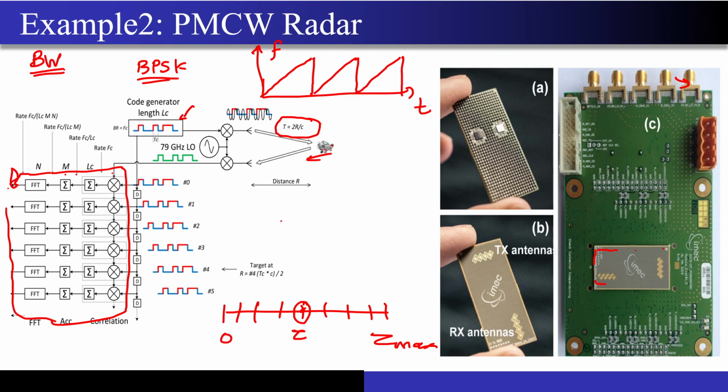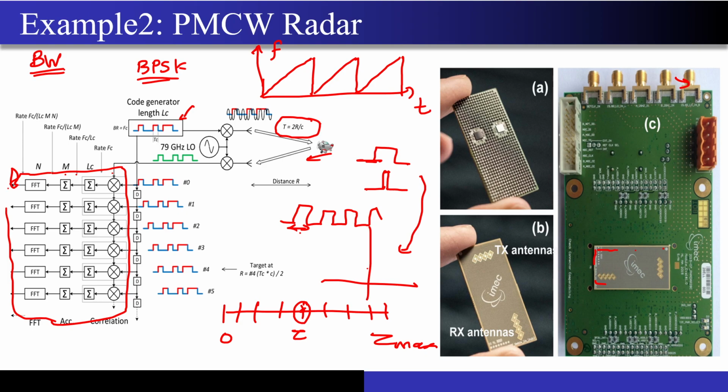So now the code that you are sending over here, if I reduce the duration of the pulse, if I take one pulse like this, and another pulse which has a very small pulse width, and now I take the Fourier transforms of both the pulses, in one case I will get a very wide sinc lobe, and in another case I will get a very small sinc lobe. I am just drawing the main lobe of the sinc function. Okay, so for this smaller width pulse, I will get this huge lobe over here. Correct? So it means that it is achieving a higher bandwidth.